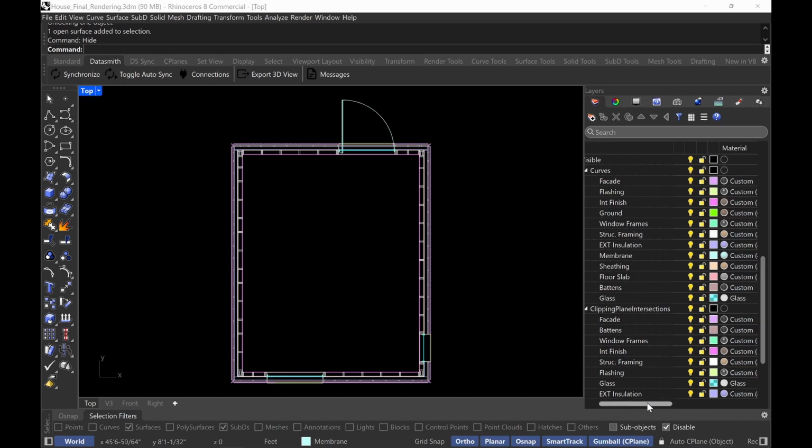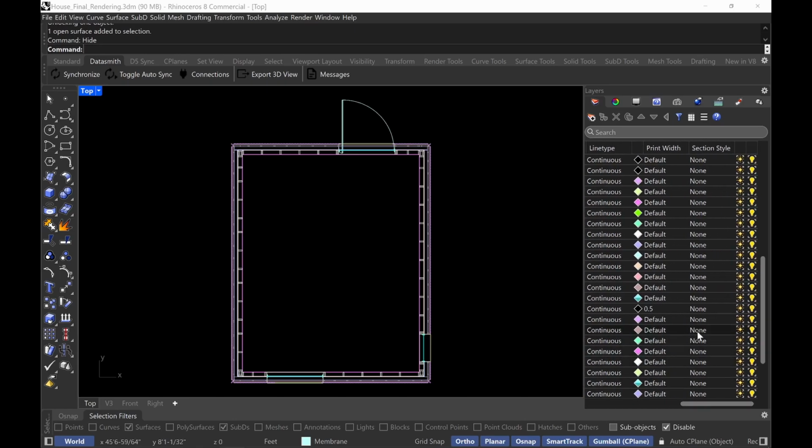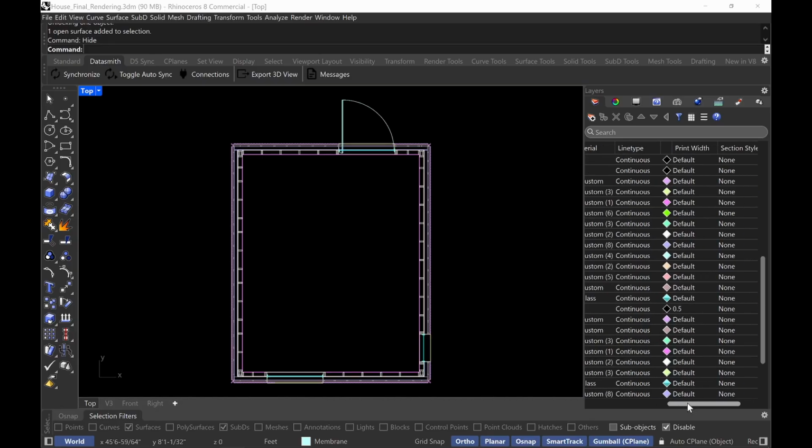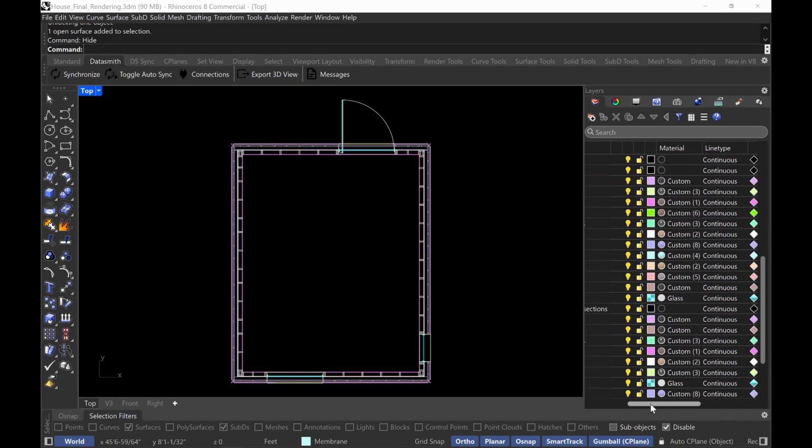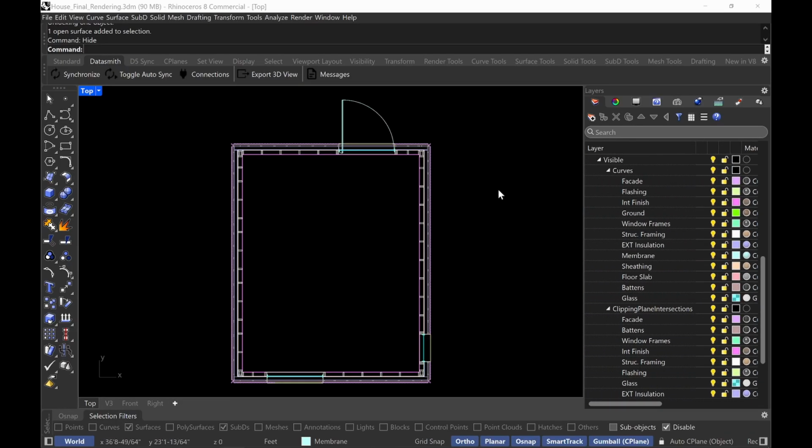So when you do your line weights, which is gonna be all the way over here, right? You're gonna set all of your line weights here, and I'll show you in the next segment, right? You know what's gonna be heavier than the other layers. Like these are gonna be all light. These are gonna be a little bit heavier. These are all cuts. And again, I'm gonna go into detail about this in the other segment. Okay, cool. So I'm going to transition over to now how to start creating line weights and how to set this up in Rhino. Just keep in mind that when I transition over, you're going to see something way more detailed with like way more walls and trees because I put a bunch of blocks in there and I'll show you where I got all that stuff as well.